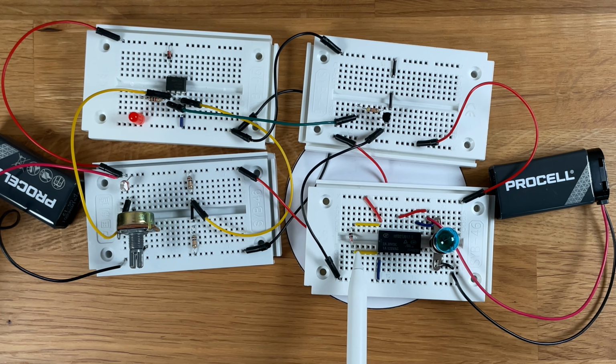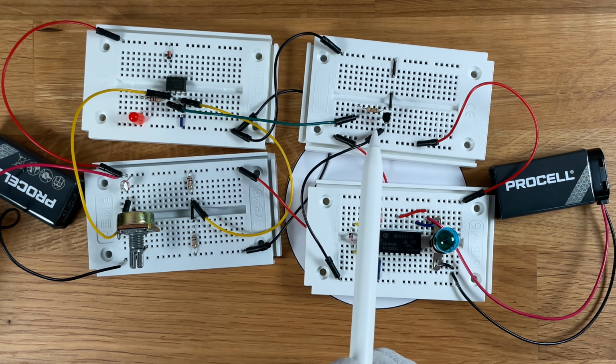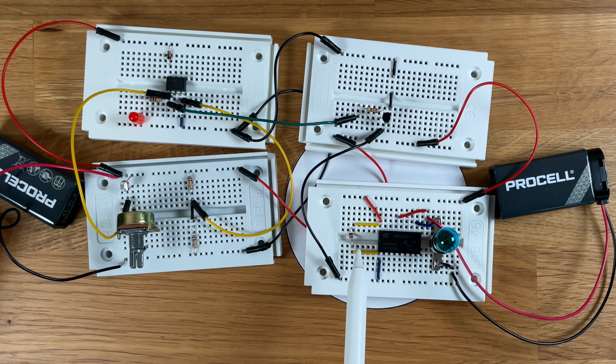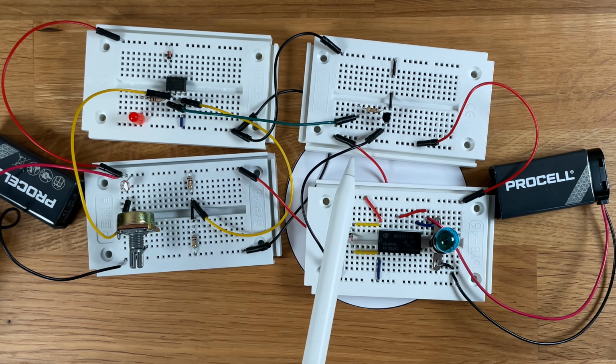In case you're wondering what this diode, or this element here, does, this has not yet been discussed. It prevents energy which is stored in the coils of the relay from being output unhindered, unchecked, through the rest of the circuit, which could damage the transistor. We will look at the energy storage in coils in a few days by using an oscilloscope. But for now, the only thing you need to know is that this is needed. If I take this one out, I am endangering the transistor, which I do not want to do here.